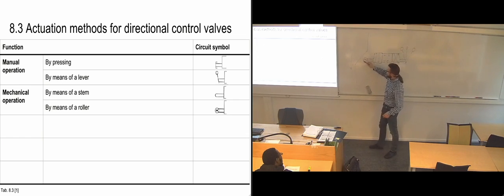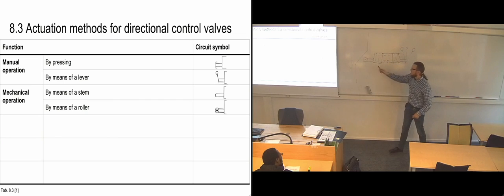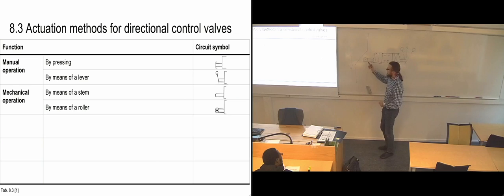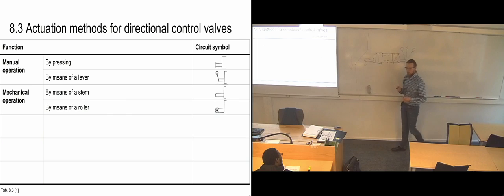And as the plate is moving down, this edge would start pressing on the wheel, which will start rotating, and it will start pressing the roller into the valve and start actuating the valve, basically. But if you did this option with just a stem like this, it would experience forces in this direction and in this direction. So you would start bending the entire stem, and that wouldn't be good.